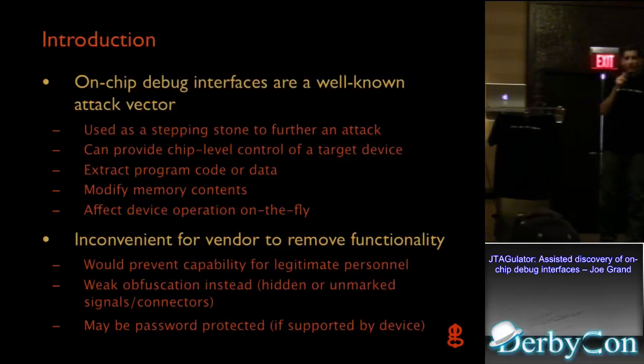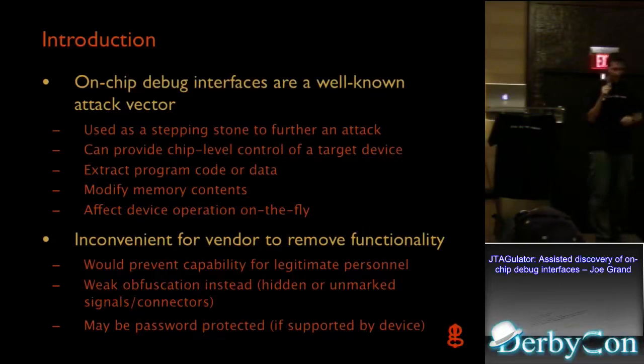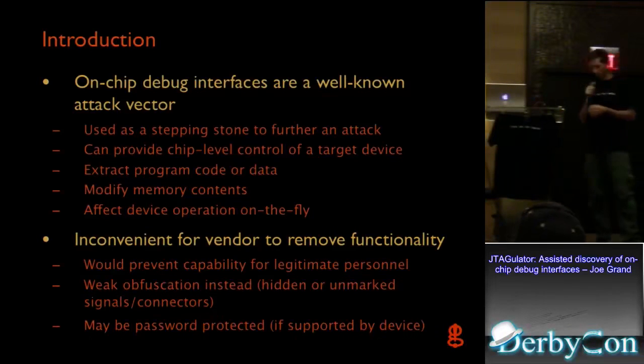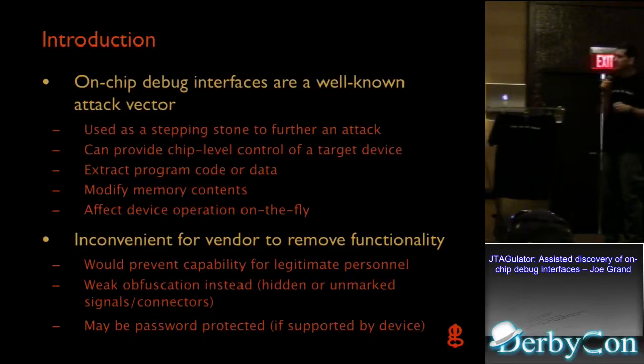So yeah, debug interfaces on circuit boards are really one of these well-known attack vectors. So if you're into hardware hacking, one of the first things you do when you open up a board, you look for the main components, and then you look for any sort of interfaces that you might be able to connect to and possibly attack or get some sort of information about the system from. So that's something that this tool is really going to help with, is trying to find those interfaces and tell you what they actually are.